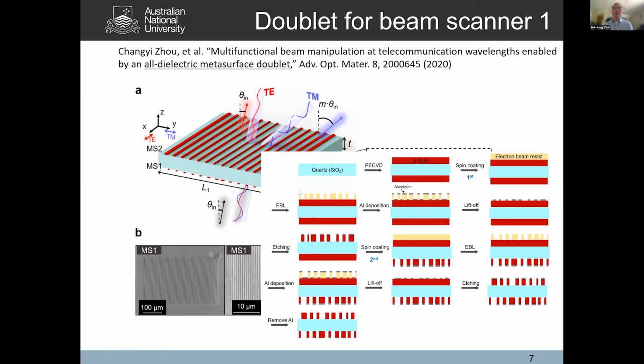It is not only composed of two rounds of nano patterning on both sides, it also needs very careful sample handling without damaging the predefined pattern. Also, exact aligning of the two metasurfaces through a 1 millimeter thick glass substrate. I use a transmission optical microscope for this alignment, and the accuracy is around 10 micron.